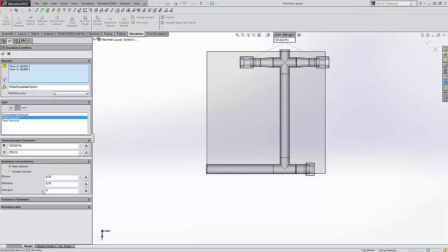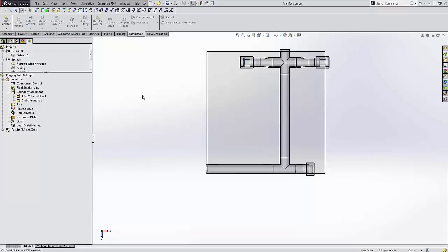When it's an outlet, that concentration that you enter in is just the starting point for the calculation. So what that means is you are not controlling the concentration out. The software is calculating that for you. That's typically what you want to know on a mixing type of project: what is the concentration that leaves.